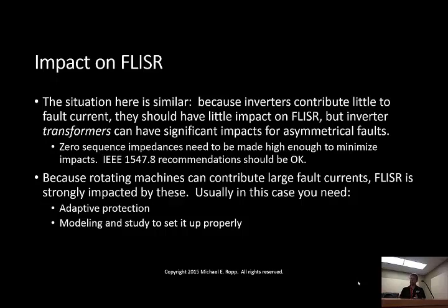Then they talk to each other on the communications network. They say, okay, who was the last one to see the fault current? And one of the relays says, hey, that was me. Then they say, okay, who was the first one who didn't see the fault current? And the next relay says, hey, that was me. So the fault is between them. And you can open these, then you can reclose on this end to pick up the head end of the feeder and close into your secondary source to pick up the tail end of the feeder.